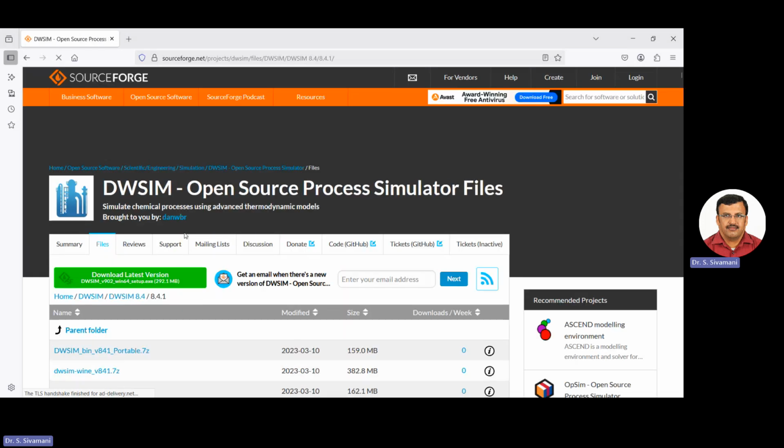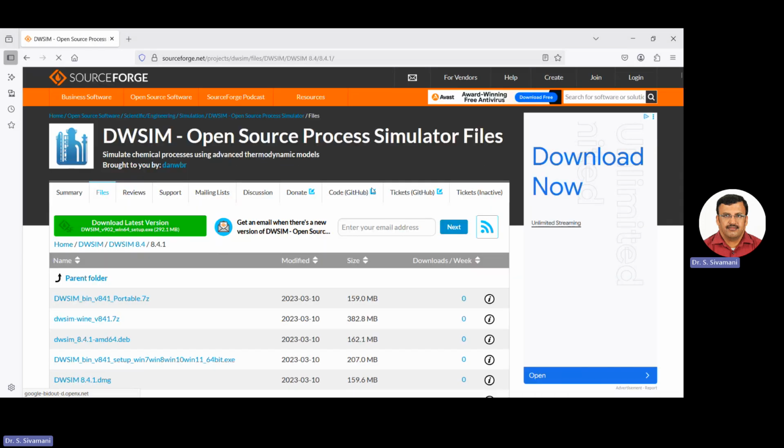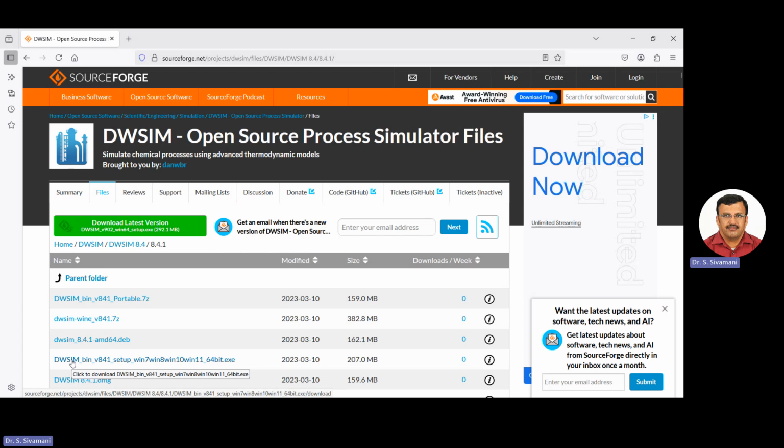Actually, whatever I am telling you now is for the Windows version, for those who are using Windows. Next, you have to click on DWSIM Win V841 setup Win 7, Win 8, Win 10, V11, 64-bit exe.